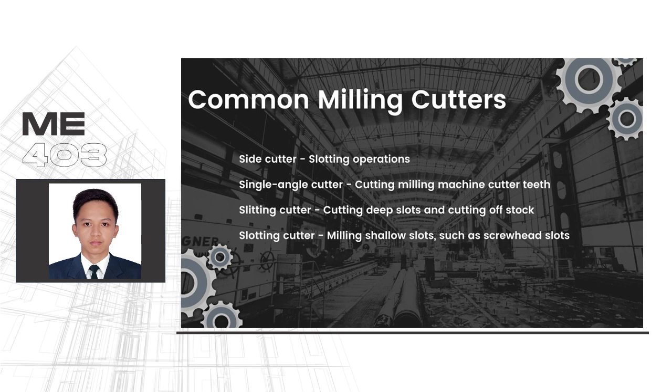Side cutter, suitable for slotting operations. Single angle cutter, chiefly used to cut milling machine cutter teeth. Slitting cutter, used to cut deep slots and to cut off stock. Slotting cutter, used to mill shallow slots, such as screwhead slots.